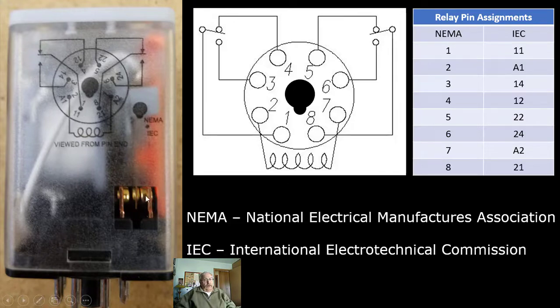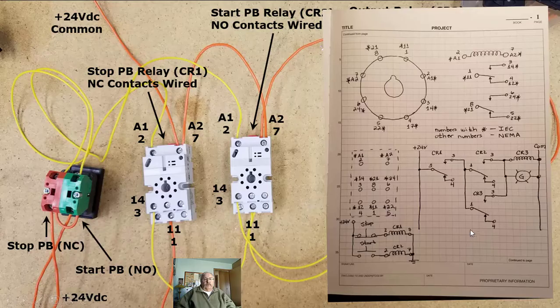Right now these are the normally closed, and when you energize the relay, this pole or this wiper will move away from this contact and close this and move against this one. So I like these relays. I get them from Automation Direct. They're affordable, whatever.